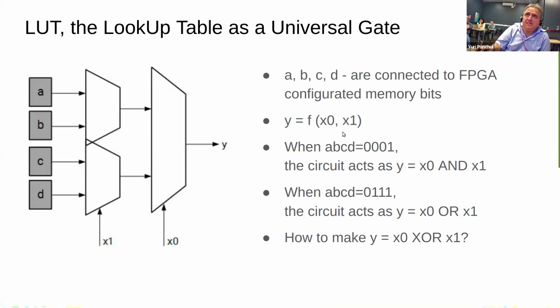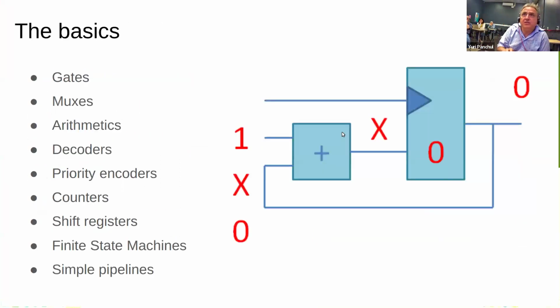So basically this is all the slides, because the rest of it I will show you. Now, the basic concept of hardware description language. This is a counter circuit example, which shows the basic idea of digital logic completely. You do something within a clock cycle, and then at the end of the clock cycle, you write it into storage elements, which is a D flip-flop.